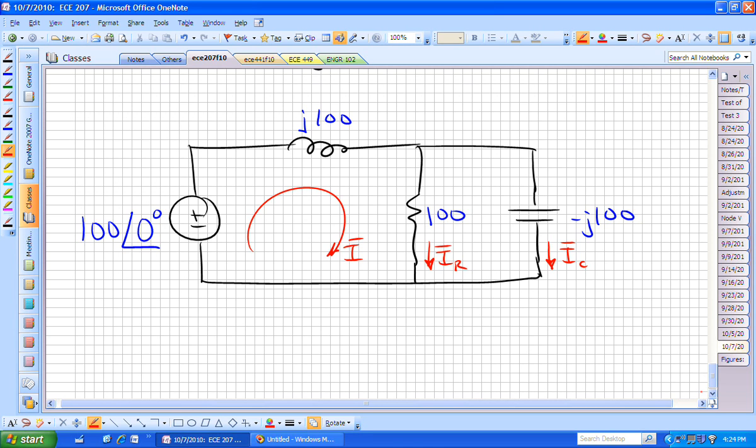Do you want to have 2 equations or 1 equation? See? You guys have learned how to analyze these circuits. You can do that on the exam. You can say, look, this looks like a mesh problem, but let me just wait a minute. If I did that with nodal analysis, I'd only have 1 equation, 1 unknown, and I could be done. Did everybody see that? Where is our node that we want to define?